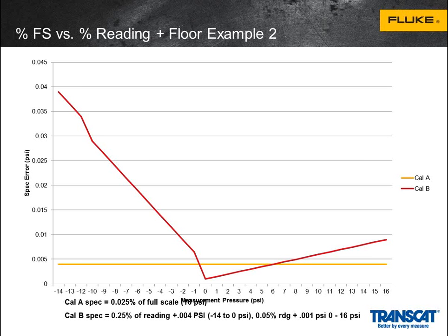And so things are not always as obvious as the previous graph, and frequently, especially if your work is right around 0 to 1 atmosphere, either vacuum or pressure, you really have to draw these graphs in order to understand which one will be better for you. This is something that you shouldn't expect a technician in the field to do. This is something that your measurement staff should really be doing for you and helping you decide.